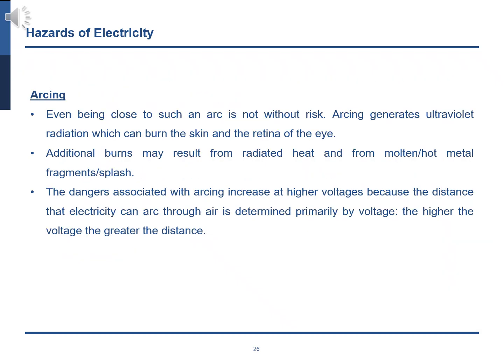Even being close to such an arc is not without risk. Arcing generates ultraviolet radiation which can burn the skin and the retina of the eye. Additional burns may result from radiated heat and from molten/hot metal fragments/splash.